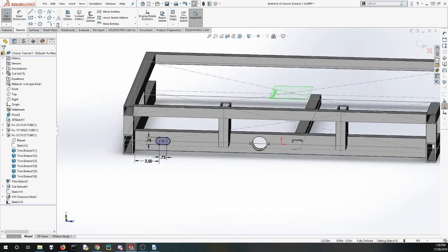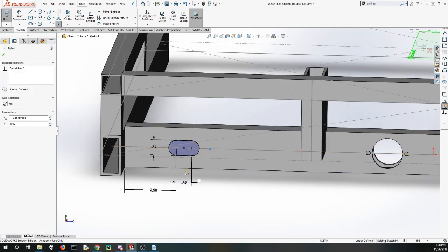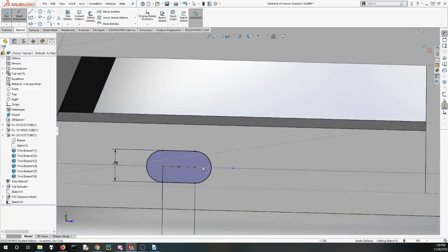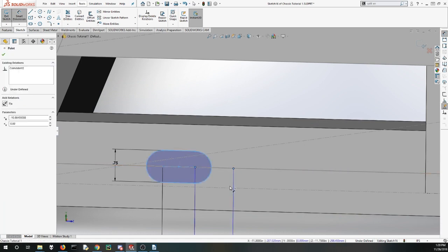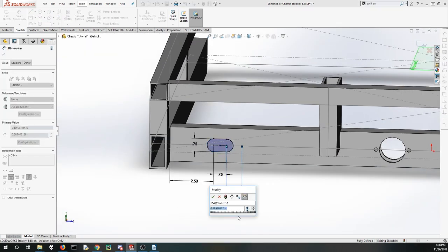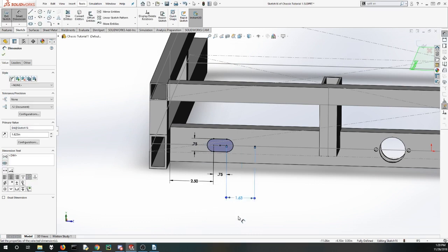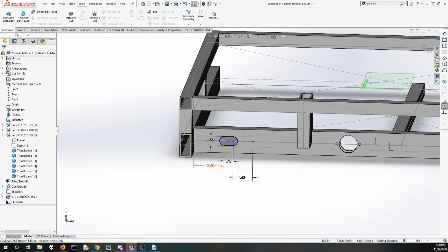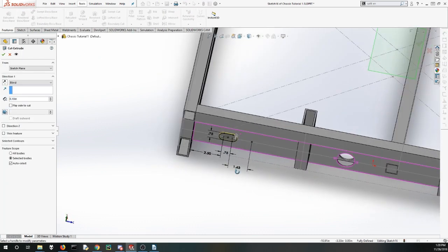Now I'm going to put a point here for the screw, which will add an extrusion. And this is going to be 0.625, which is away, I think. And these dimensions are all things you should check yourself, depending on what kind of sliding bearing mounts you choose to use and what kind of gearbox and all that thing.